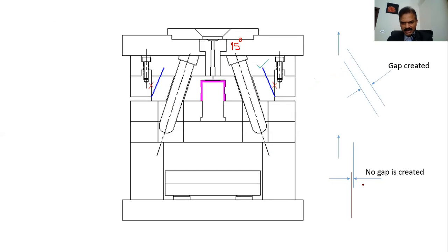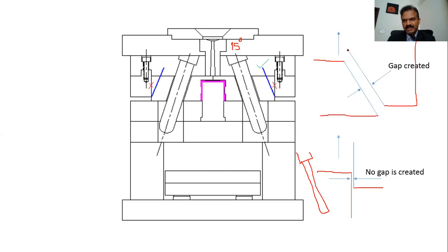So we learned from the previous slide that the tail end, if you design it straight, like right here, it goes here. If you design it straight, it is not going to leave any room for the slide to move out, right? So we have to design the tail end of the slide at an angle. So this is the wedge. I will complete the wedge here.